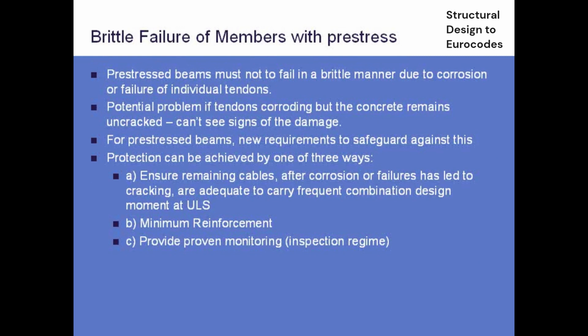As I say, if you've got very little pre-stress and a very large section, then when the concrete cracks, you've lost most of its capacity and there's virtually nothing left in the pre-stressing, so it might fail at the ultimate. If you don't want to do that calculation, then you have to put in more longitudinal reinforcement, and there is a penalty involved in that because you have to put in as much reinforcement to fully cater for the loss of tensile strength, so you will end up putting more bars in there. So it's best to use method A.